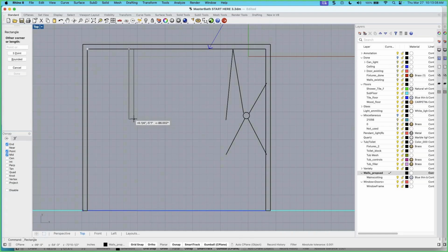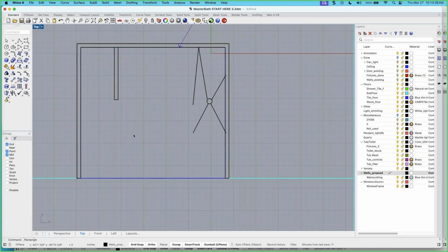So what else do we know about the interior wall? First, as we move in the X direction, it's a positive 4 units. So I'll enter that. And the length of it is negative on the Cartesian system. So if I type in minus 4'8", it's going up, not down into the plan. So I can correct that by typing in negative 4'8". And all I have to do is enter, and I now have that interior wall.